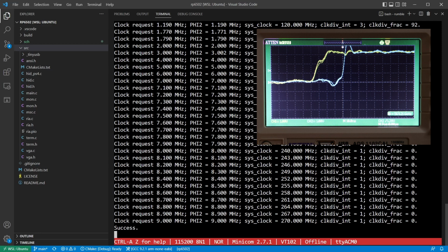You can see on the scope that the 50 nanosecond delay from before is down to 35 nanoseconds. In fact, we're hitting 9 MHz. I'm very happy with this outcome. Requiring AC chips for 8 MHz is reasonable, and support for slower HC chips is easy enough by defaulting to 4 MHz. The Pico computer can self-test and let 6502 software know if faster speeds are available. There's 2 more things to nail down before I make a circuit board. The RAM chip will be running code next time,